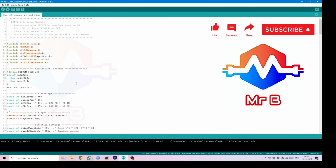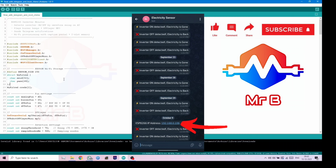So what I have put in this option is that whenever the first time that you flash the device or the ESP with the programming, you need to hard code it with a Wi-Fi credential as well as the passwords and SSID and everything. So what happens is that for the first time it boots up, in your Telegram bot, in the chat section, you will get an IP address thrown out by the ESP to the Telegram bot.